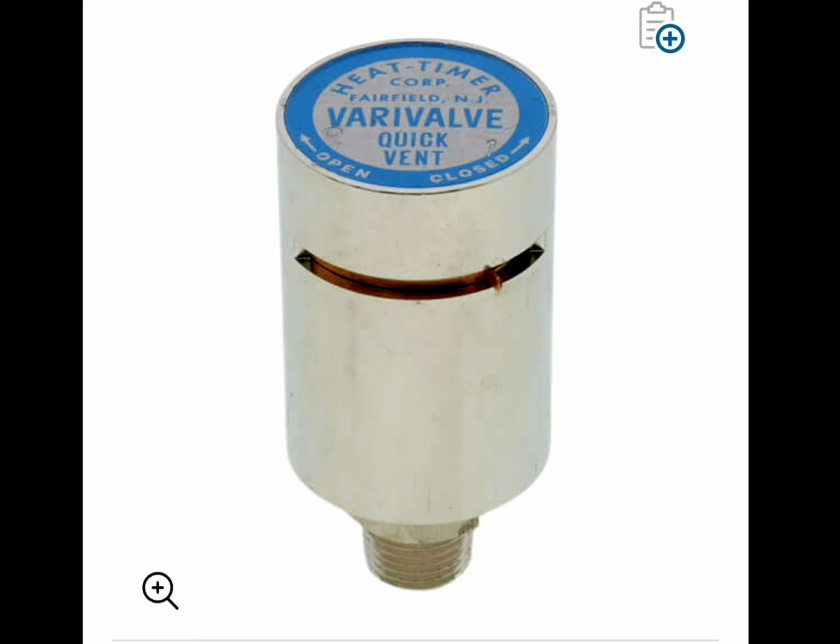The next thing I've noticed about this air vent is when they go bad, it typically just freezes and no air can get through it. And I had this problem happen in that home that I lived in for a whole winter straight. I didn't have heat in my room. Everything else got hot. I had nothing going on in my room. Now, occasionally, periodically, the radiator would heat up and then it would just start slowly dying down. And that was it. It wasn't until the next heating season that they decided to finally change the air vent, and then that problem was done for.